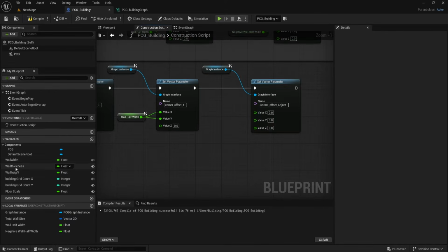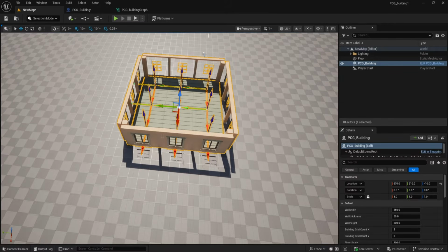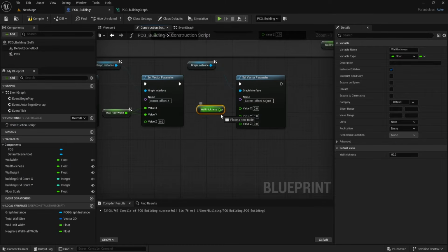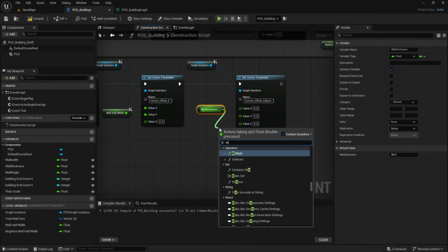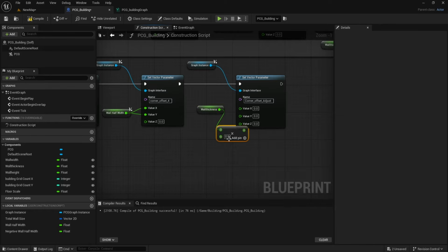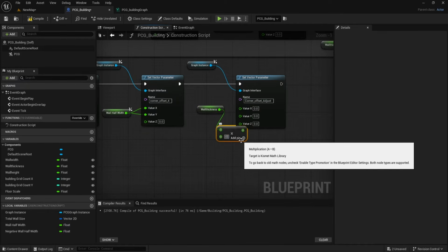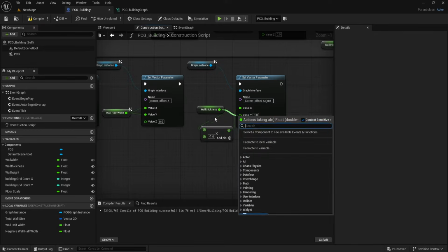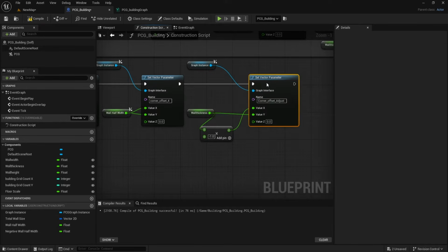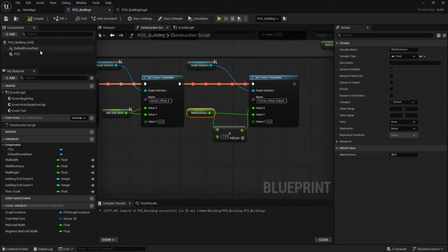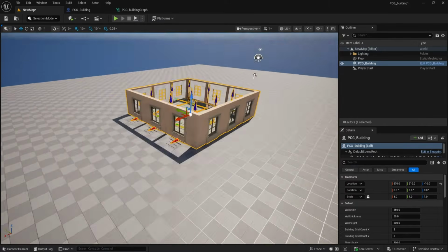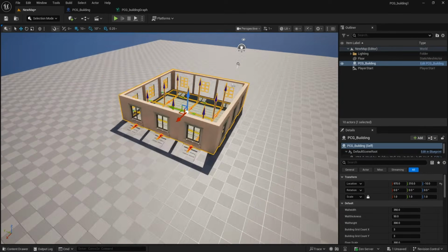For the placement, you can see on the level, I have to take wall thickness on Y positive and negative on X. So I will take wall thickness multiply by -1. Connect the minus one to X and positive to Y. Compile and save. Force region and save it. Go to the level. You can see corner pillars are placed correctly.